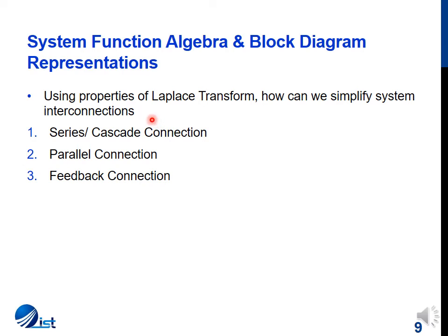We saw 3 system interconnections. Firstly, the series or cascade connection, and using the property of convolution, we saw how a series or cascade connection can be combined into a system which is a product of the transfer functions of all those individual systems.